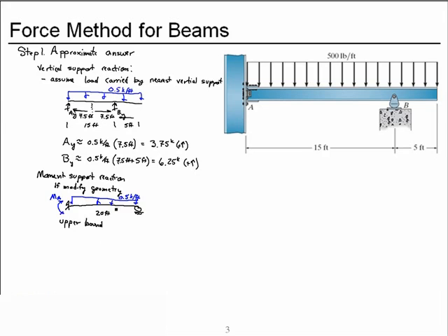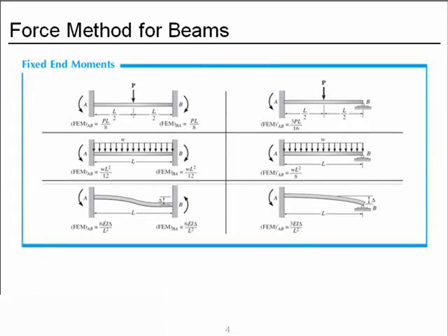Now, it won't be as big as if it was cantilevered with no support, but this provides an upper bound on the moment we can expect. And this is a special case that we can find in the back cover of our text. So if you have not explored that part of your book yet, there are indeterminate structures shown in the back cover, and it has pre-calculated the moments at the ends of those special indeterminate beams, called fixed end moments.